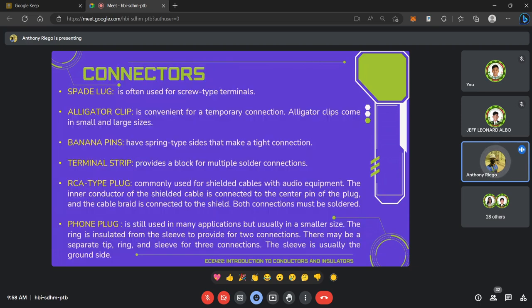You have also your RCA type plug. It's commonly used for shielded cables with audio equipment. So, ayun nga, pag mga audio na, you have your RCA. Pag mga nag-check din kayo sa hardware stores, tinatanong yan, RCA ba yung gagamitin mo? The inner conductor of the shielded cable is connected to the center pin of the plug, and the cable braid is connected to the shield. Both connections must be soldered.